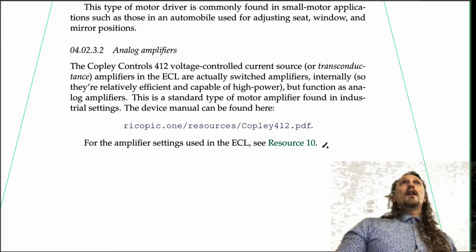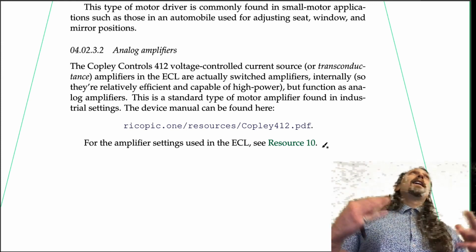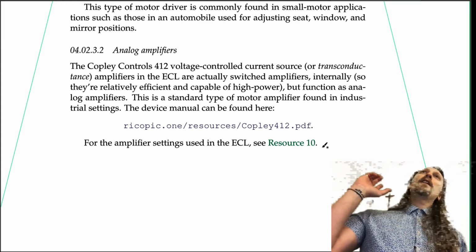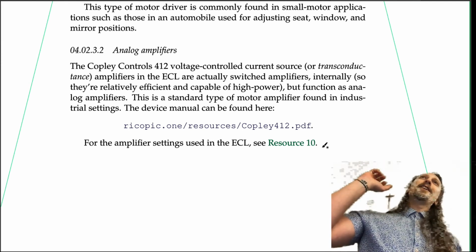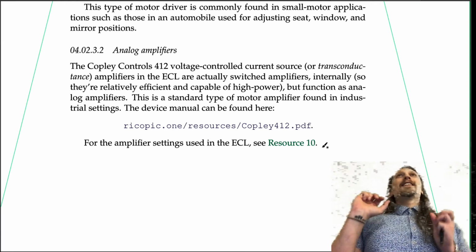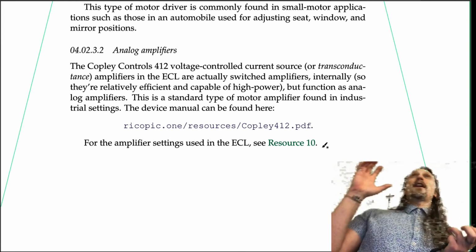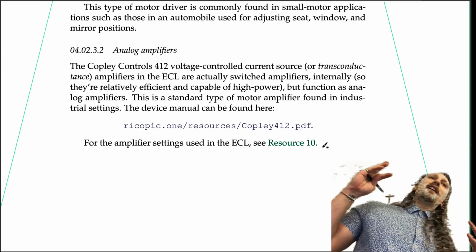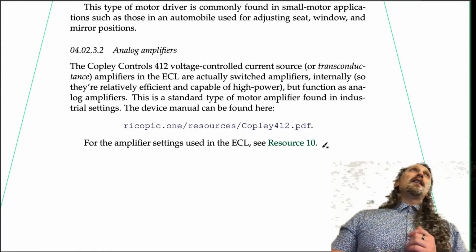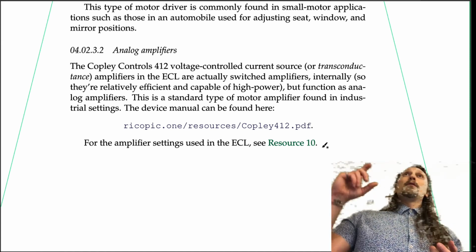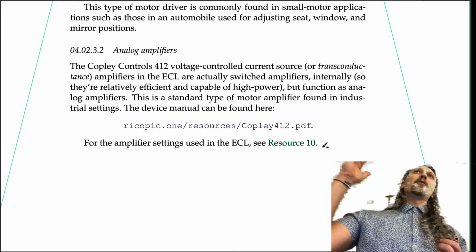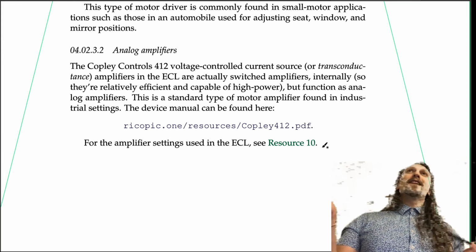A stepper? Yeah. Well, it's tough to know what's going to happen if you don't have enough torque. If you send the pulse and it doesn't turn, it slips back. Yeah, so if you can't make it over to the next slot, then it's just going to stay where it is, or it'll try to move and get stuck. So this is part of why, if you try to do position control with steppers, you still often need to measure what's actually happening, because you'll send pulses and they won't step every time. They step most of the time, but they don't step every time.